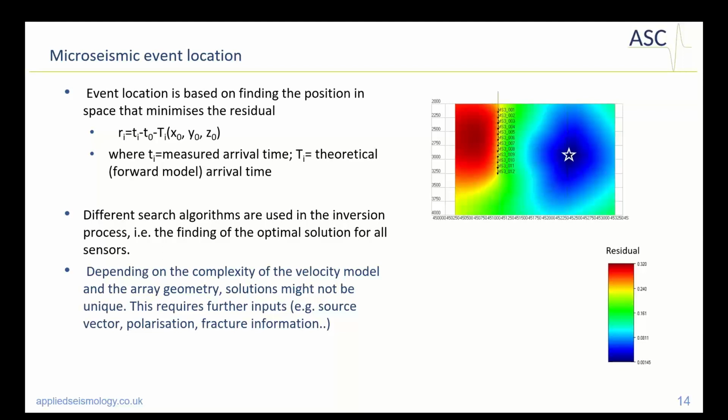So you know what your source is, if it's displacement, velocity, or acceleration, and compare that with the response on your sensor. So that's the standard calibration. And then you know what will be the correspondence in between the voltage that you're measuring and the input vibration that you have in your sensor. Many sensors are calibrated, but it's not typical for piezoelectrics to have that.